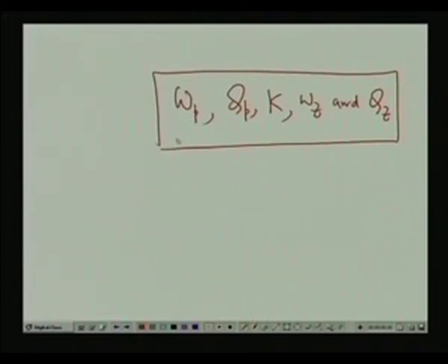Orthogonal tuning means that if I use some resistance to tune, I will consider the resistance. Suppose I want to change or modify or tune this omega p. By changing some resistance to tune omega p, the other filter parameters should remain intact. That is called orthogonal tuning.